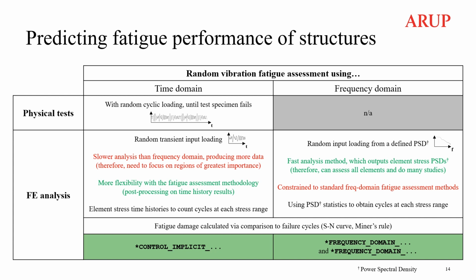The frequency domain approach is a much faster analysis and produces a lot less data, therefore results for all elements can be requested, and it is easier to do lots of design iterations and sensitivity studies, but we are constrained to a few standard frequency domain fatigue assessment methods.